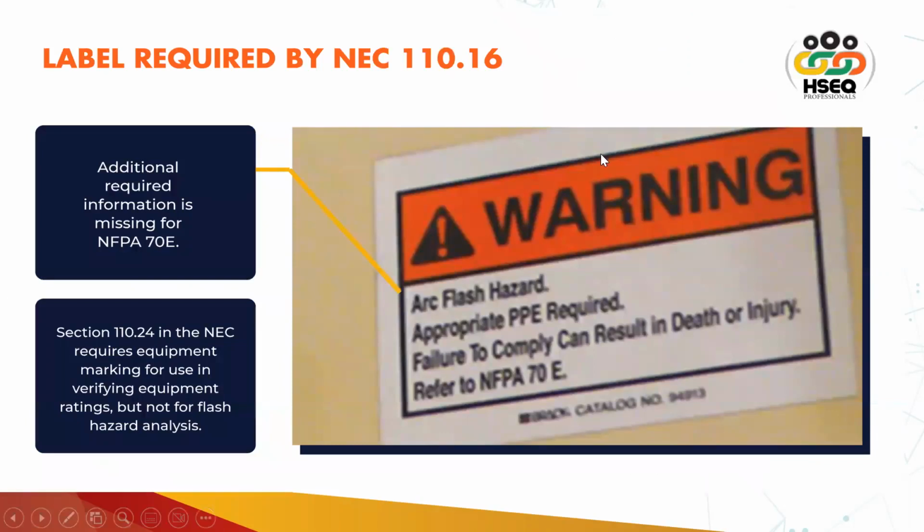They will ask in an exam whether this type of label conforms to 70E requirements. So the answer is no, because it is not talking about the shock risk assessment or arc flash risk assessment, either based on the incident energy analysis or the PPE category method. It might fulfill the requirement of NFPA 70 or the NEC, but it is not fulfilling the requirement of NFPA 70E.